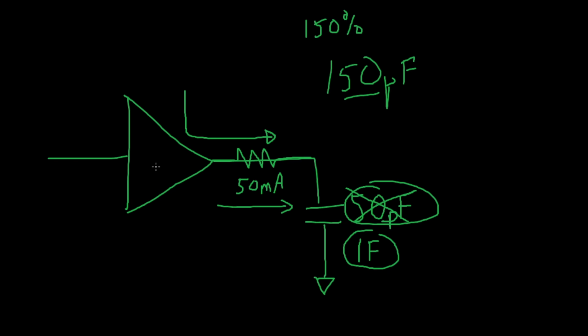That's going to take a long time to charge a 1 farad capacitor, but it also will protect our device from being damaged. If you need to be able to do something like this that's kind of absurd, most likely you should be looking somewhere other than a logic gate for your driver, perhaps with some sort of discrete power MOSFET. Now the last and what I would consider the most interesting case is whenever you connect a logic gate to a transmission line.